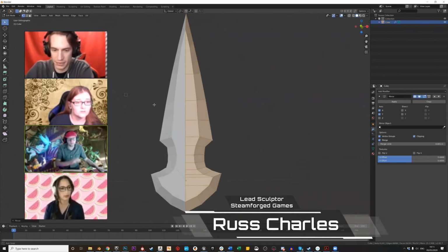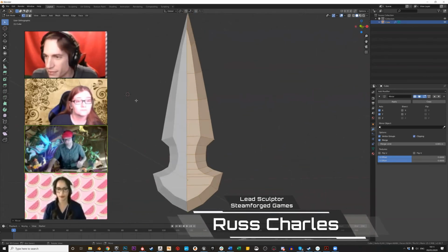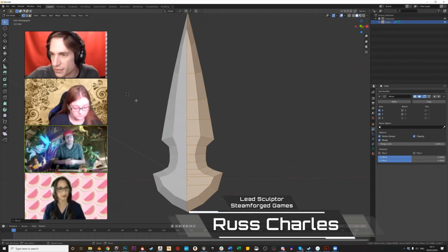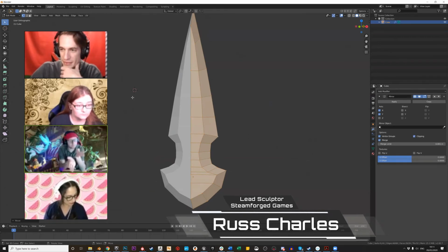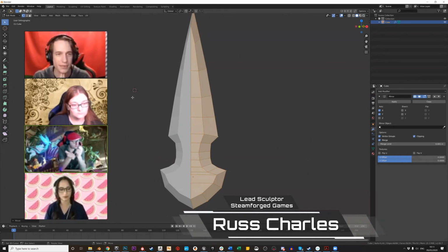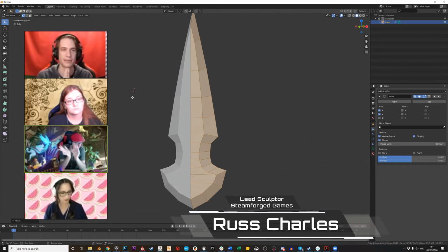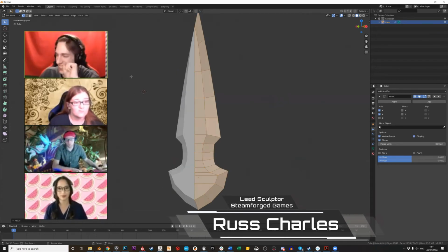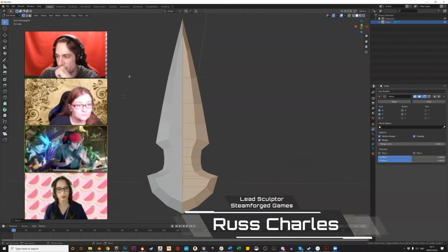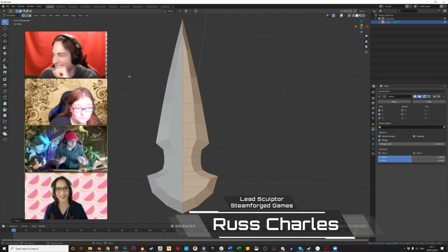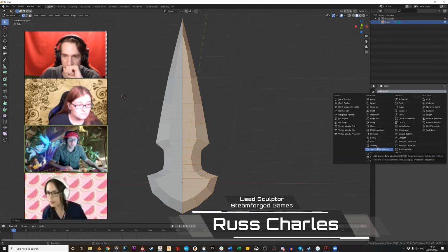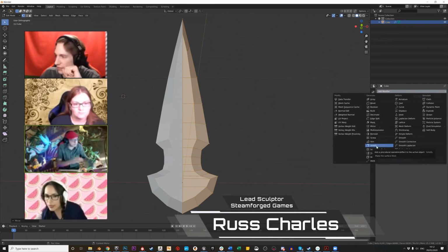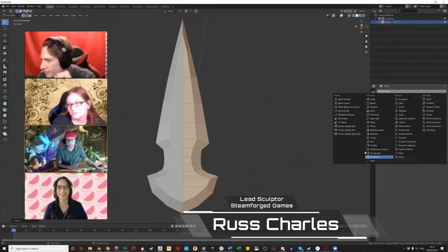Absolutely fine. We're going to do one more thing to our blade now, and we're into advanced territory. At the moment we've got the shape of our sword, but it's very faceted and looks quite crude. So now we're going to make it look silky smooth and really awesome. I'm going to add a new modifier, and I'll warn you now, when I first add this, the blade's going to look terrible, but go with me. I'm going to go to add modifier and choose subdivision surface, which basically splits the shapes down into smaller and smaller surfaces.